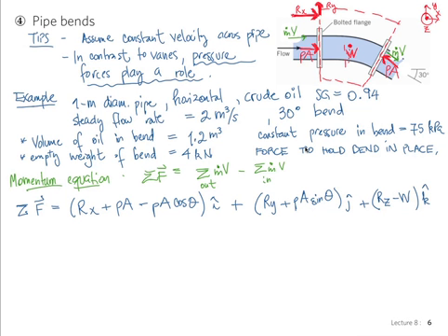So, as a rule of thumb, would you just put the forces due to fluid pressure normal to the control volume anywhere? Yes. Always. So to repeat that, what he said is forces due to pressure always point inwards, normal and inwards to every control surface. Always pushing on every control surface, yes.